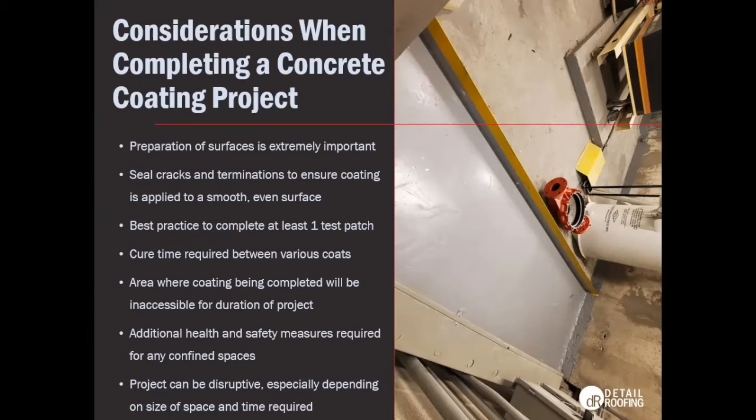Something to consider is that between each of the coats, there is cure time required. So that could extend the length of the project. And again, the area where the coating is being completed would be inaccessible for the duration of the project, not only when workers are actually on site doing the project, but again, because of the cure time, you don't want anybody walking through there or anything moving through there.